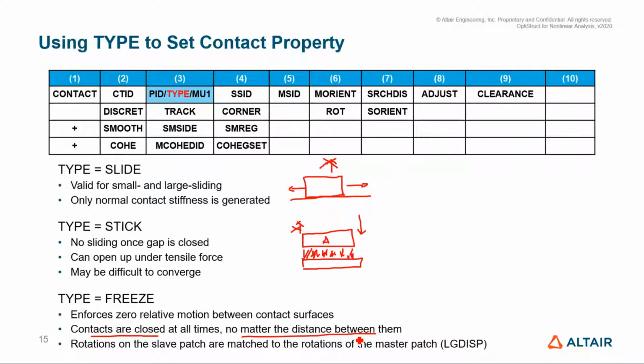Here we say no matter what the distance because even if, let's say, your part has a very large gap like this, let's say the gap here is 5 mm, right? 5 mm gap. If you put your search distance here to be 5 mm, we will establish that contact even though you see there's an actual gap here.